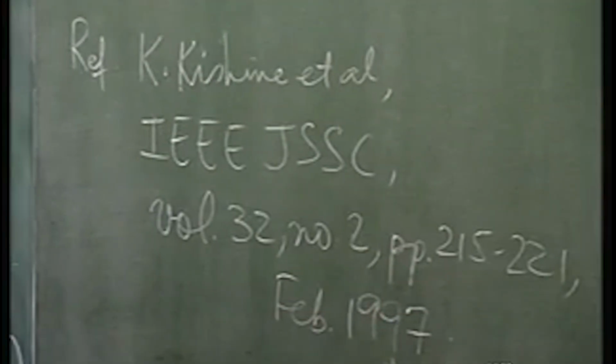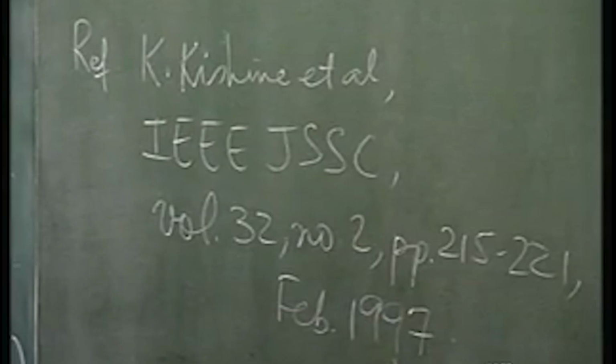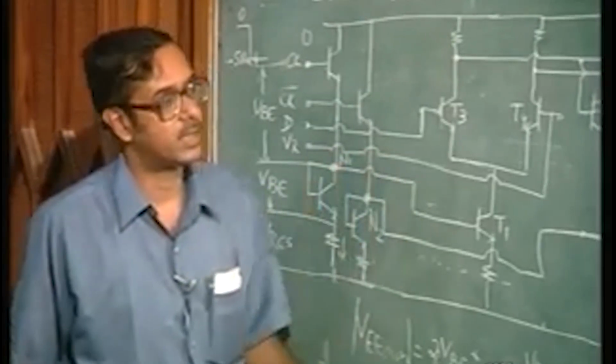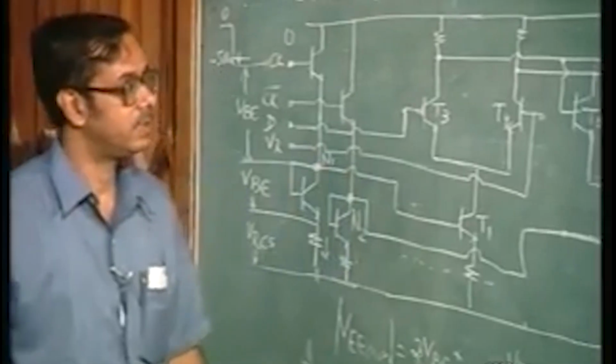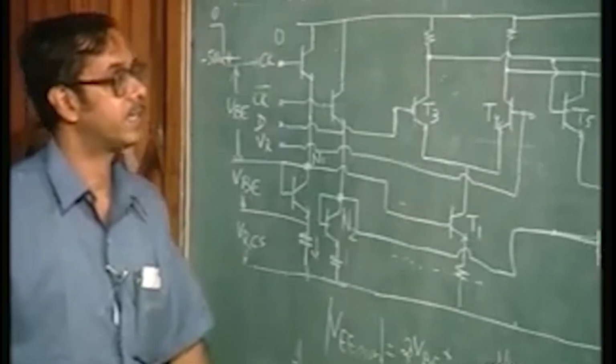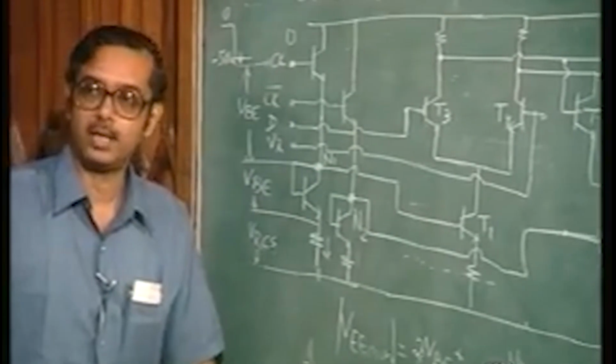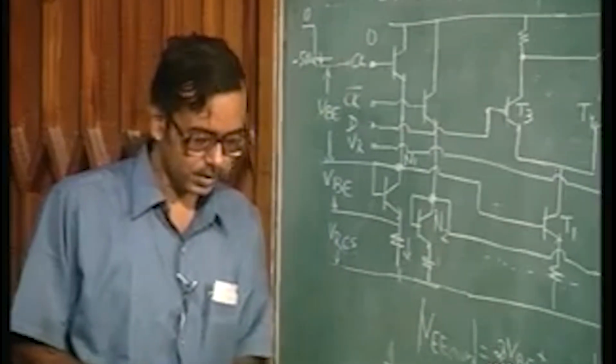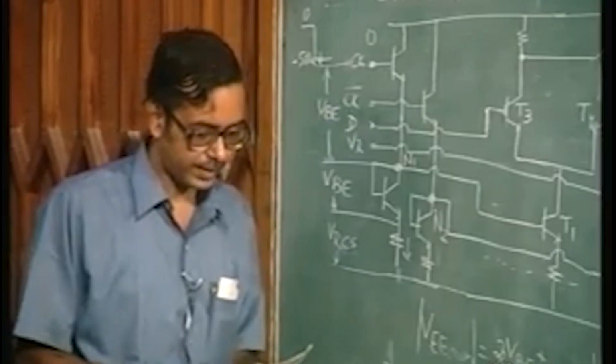Okay. So, this is a new logic family, a variation of the ECL, where you achieve a lot of reduction in power dissipation, which is the stumbling block in ECL. And with this advancement, one hopes one can really realize LSI level circuits using ECL. That is what they claim in that paper. Okay. All right.